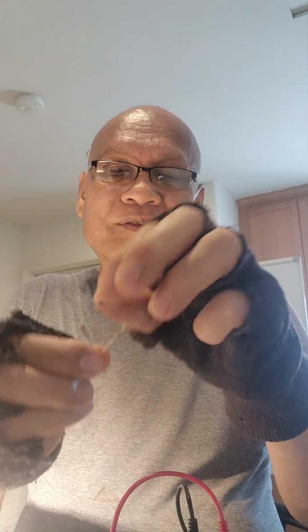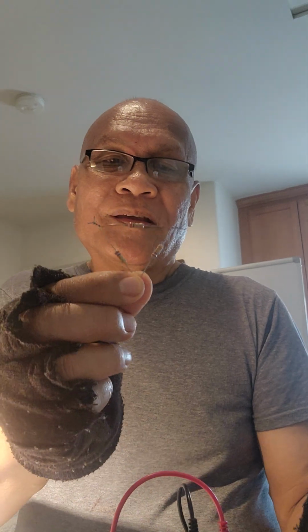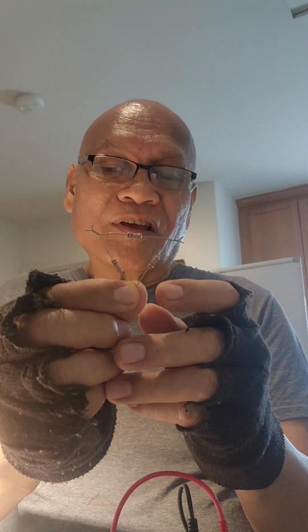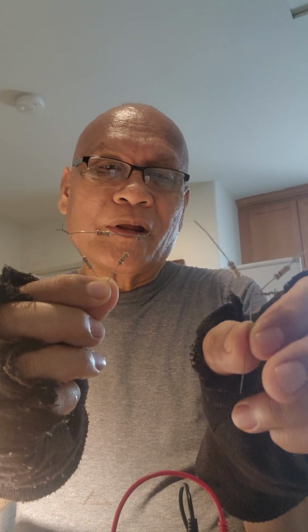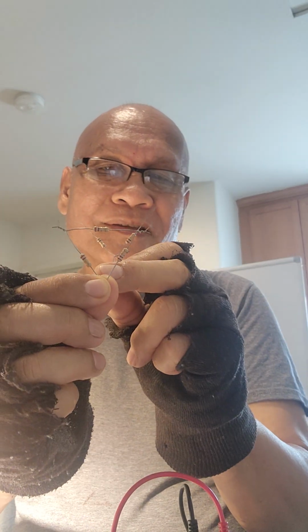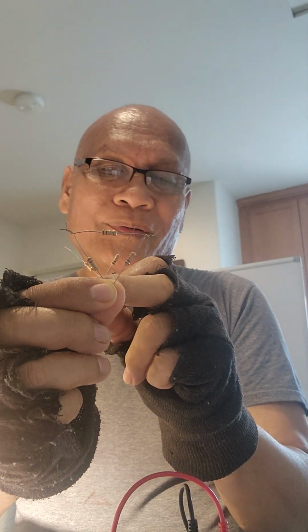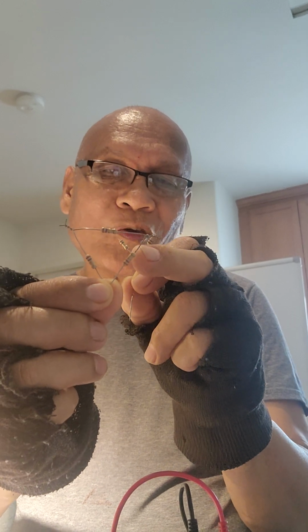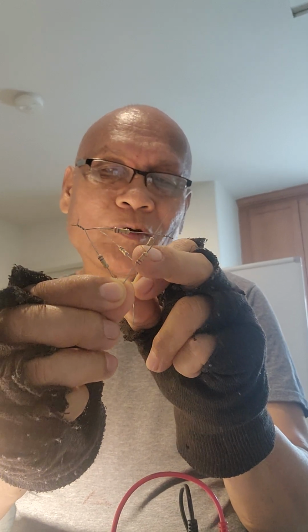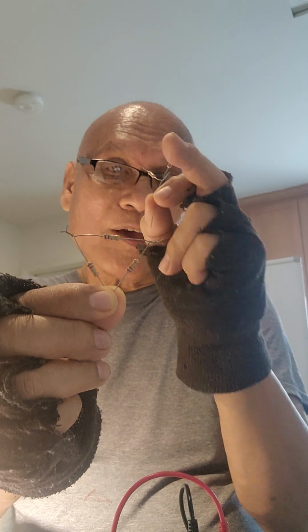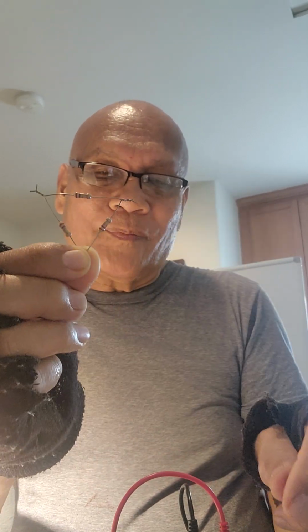And on the delta side, these are the delta equivalents now. These resistances are now 3 ohms, 3 ohms, and 3 ohms. This delta here is the equivalent of this Y. And according to our computation, the resulting equivalent of each will be 3 ohm, 3 ohm, and 3 ohm. So I assembled a 3 ohm, 3 ohm, and 3 ohm.